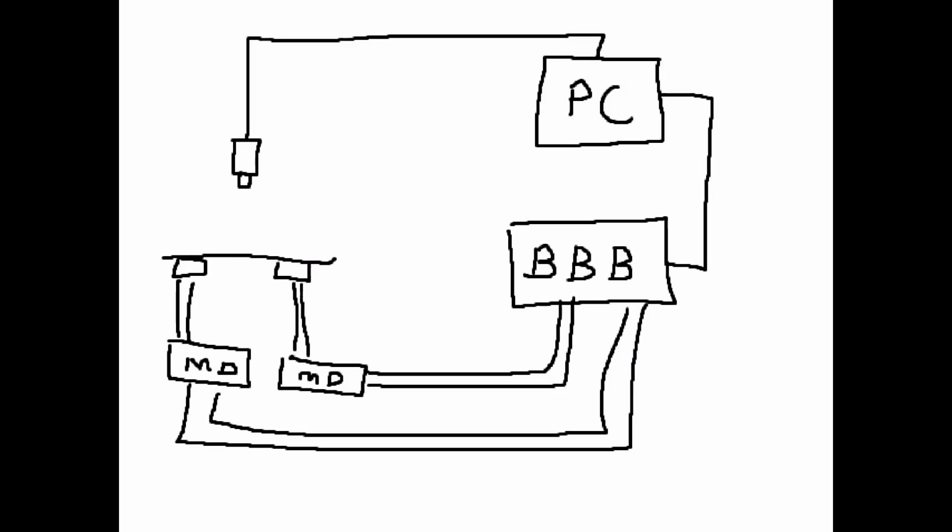Here are the motors. The driver modules convert the signals from the Beaglebone Black into power and are connected to the motors to make them turn. Currently, for DC motors, the DRV8838 from Pololu is used, and for stepper motors, the Pololu DRV8834 is used.